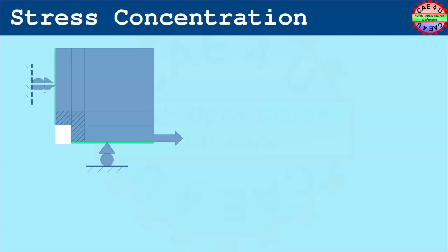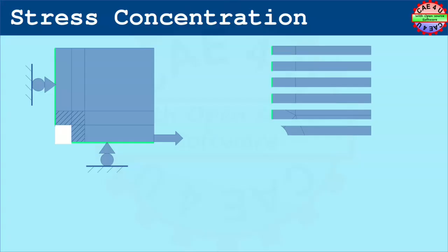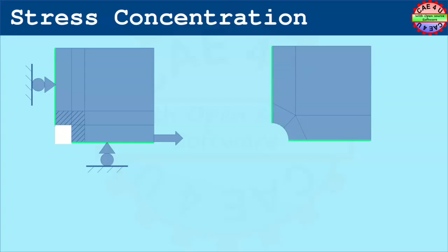The nature of the loading and the stress pattern is expected to show a plane stress condition. So it is sufficient to model only quarter 2D geometry, and we can apply the symmetry conditions by constraining the central plane. For a 2D case it would be normal to corresponding plane as shown in the picture. Though we refer to it as plane in physical sense, it will be a line in the computational model.